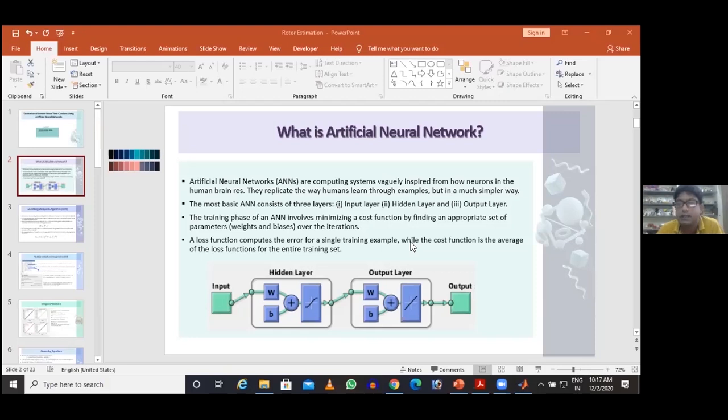So what I was telling is that it is very difficult to decouple the current which is producing flux and the current which is producing torque. That means we want to analyze an induction machine, an asynchronous machine, analogous to a separately excited DC machine. If we are able to do that, then I can operate the induction machine also as a separately excited DC machine, which is called vector control of induction machine. Why I told this story is because we need some specialized application